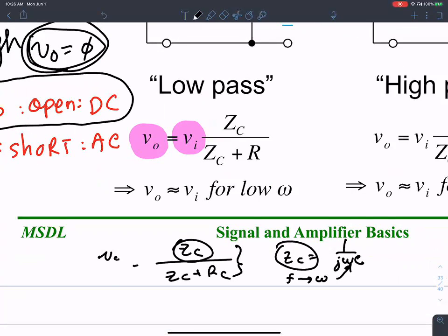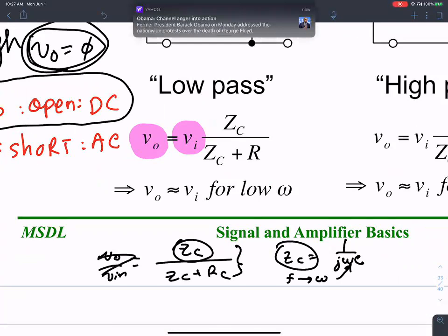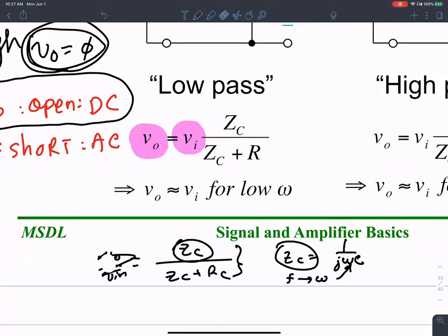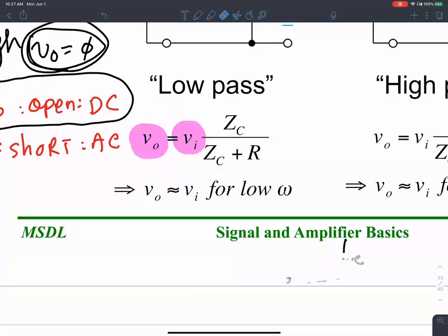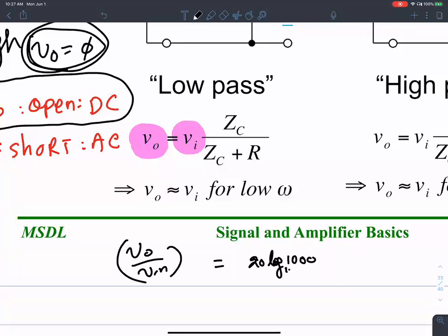Well, that's part of the process, and I think that I already figured it out. What I cannot fully understand is how to go from that to get the decibels. Once you have V out over V in, let's say that comes out to be 1000. All you have to do is 20 times log of that. So that is going to come out to be 20 times log 1000 base 10, which is 3. So it's 60 dB.